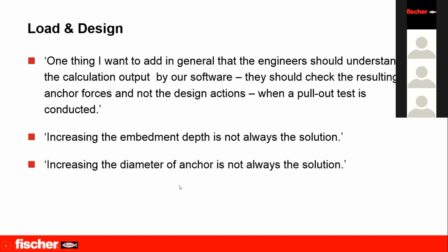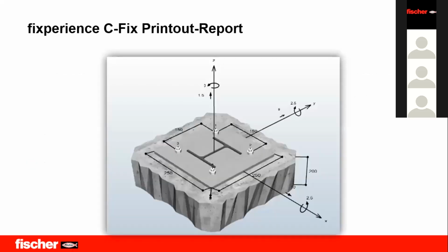Also, increasing the diameter of the anchor is not always the solution, because it will be affected by other factors like concrete cone failure. So it is not always the solution to choose the bigger size or the longest embedment depth.